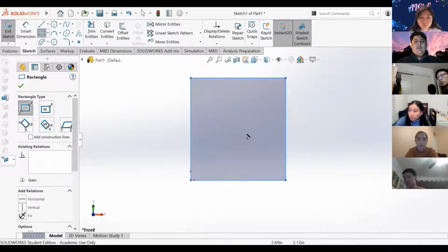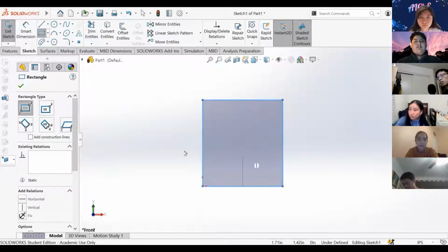You scroll the wheel up and down, and eventually, when we get to 3D, we'll be able to orient this object with the wheel as well by clicking it. So cool. We have a box now, and if you notice, the whole entire sketch is blue. What this means is that our sketch is underdefined, as you can read down here.